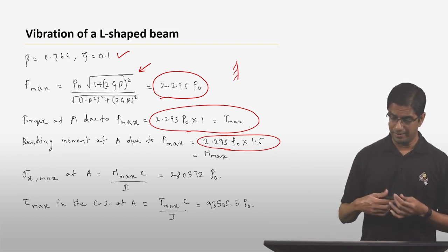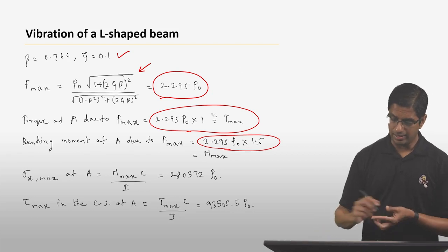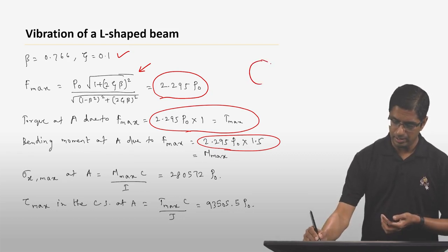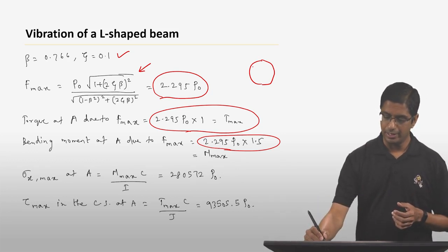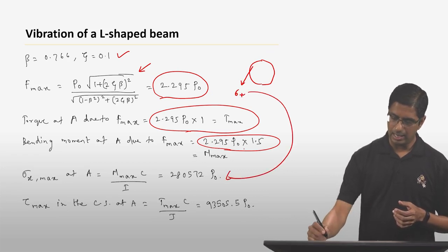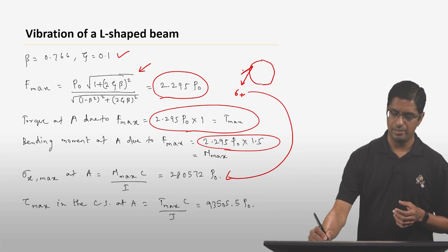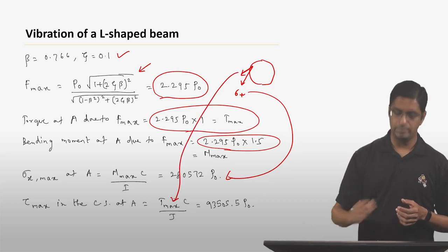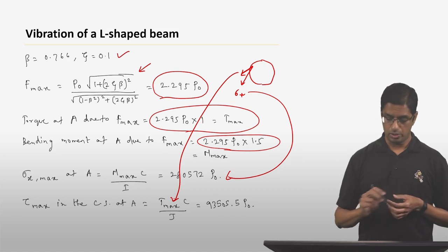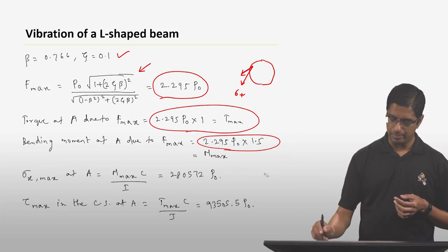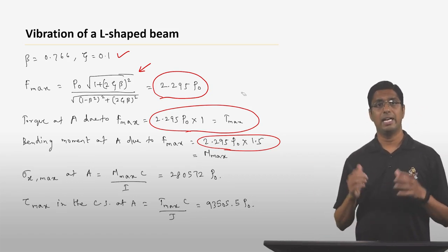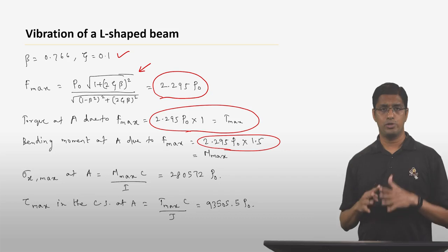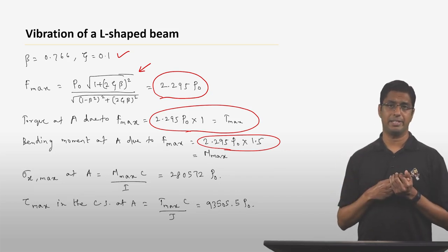If you look at the circular cross section at A, at some point, and we don't have to worry about which point, you are going to have a sigma x given by this, and also a shear stress given by that. Those are the bending and shear stress, or the normal and shear stress, acting at the most stressed point at cross section A.